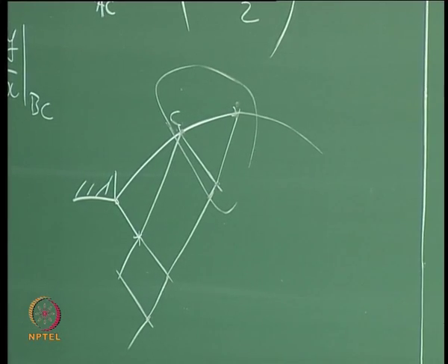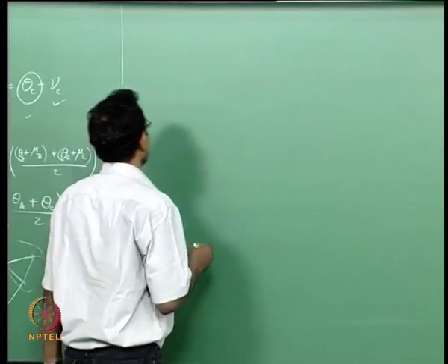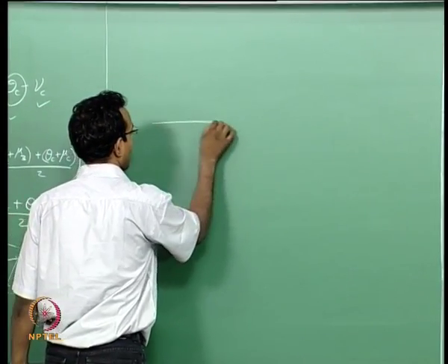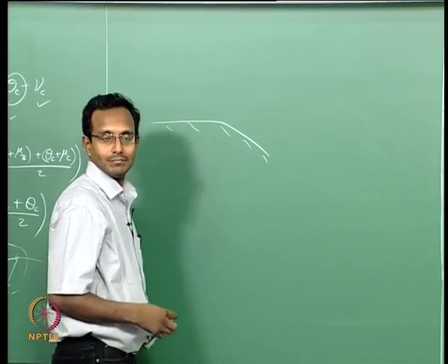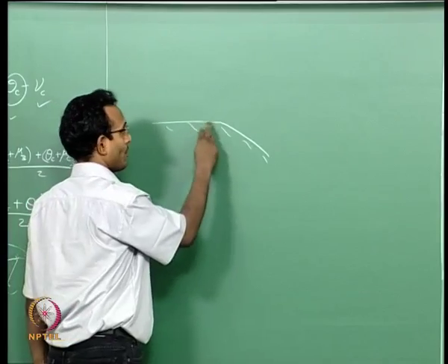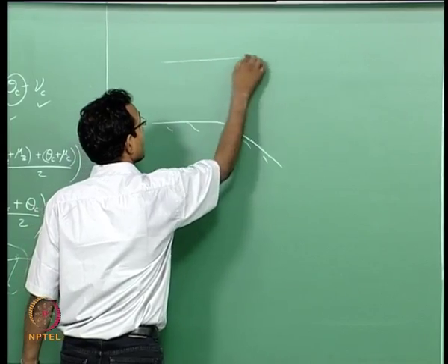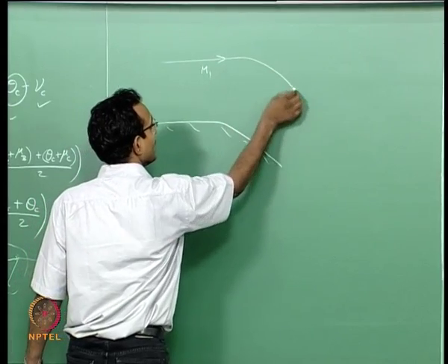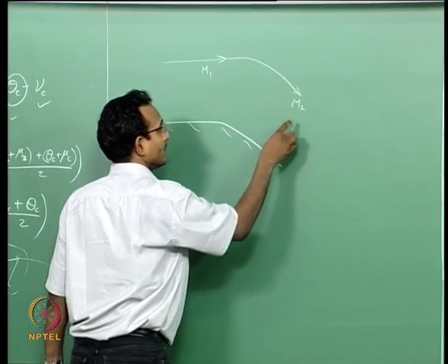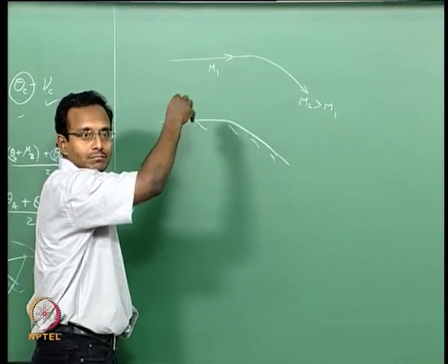Okay. So, we have given you simple cases. Now, I just want to discuss a little bit before I go back and give you more routines. Say I have a flow and the flow is supposed to be expanding. What do we expect in this case? I am drawing it as if it is a smooth expansion, does not matter what I want to do. I am thinking about some case here. Here the Mach number is m1 and eventually it has to turn and become some m2, which is greater than m1. This is what we expect, somewhere up there, right.